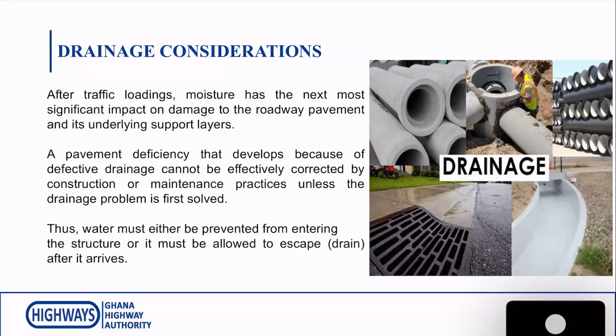It's lower than the sidewalk and the inlets that allow the water to flow. The inlets are all silted, and the water cannot flow out through the curbs and the gutters into the drainage system. So anytime it rains, the water stays there, and it's a problem. Unless we solve that problem caused by drainage, whatever one does there by importing material cannot resolve the problem.